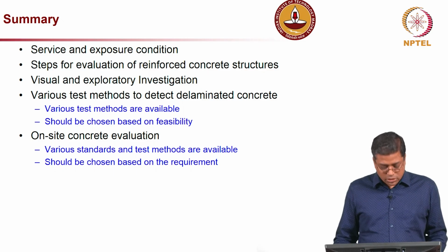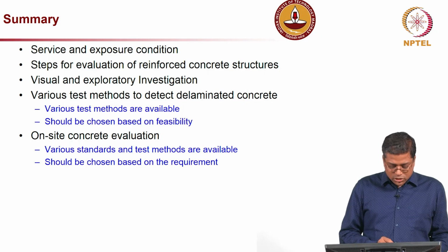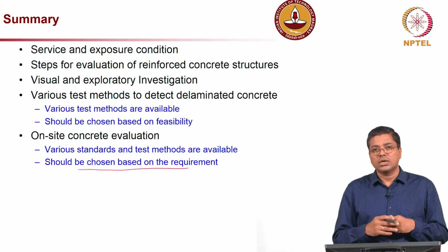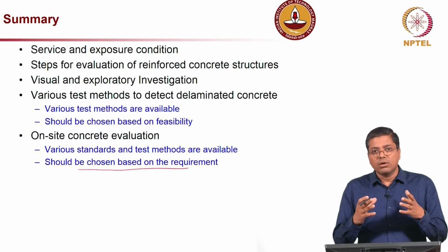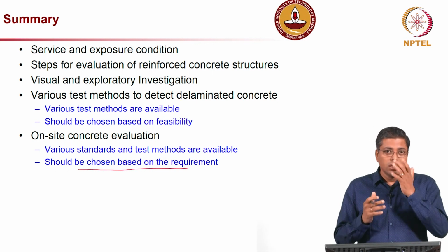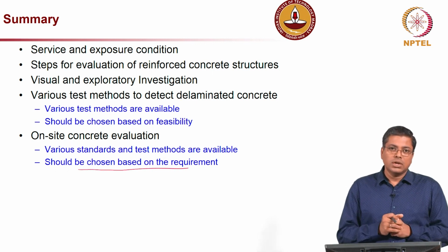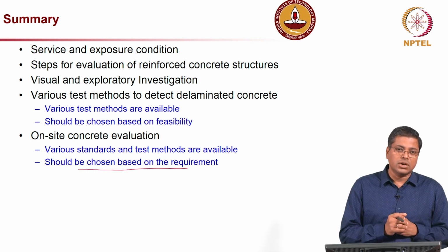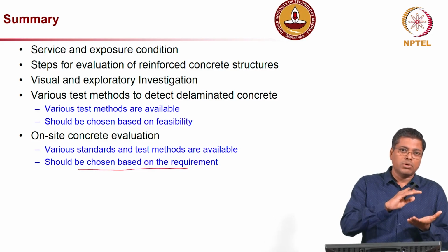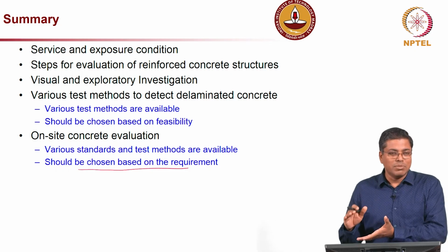I gave you a list of those, and the method should be chosen based on the requirement. It is not that all non-destructive testing techniques are good everywhere. The type of instrument which we select should also be able to give sufficient resolution of the images for that particular application. For example, if you are talking about a very thin element, some instruments may not work.